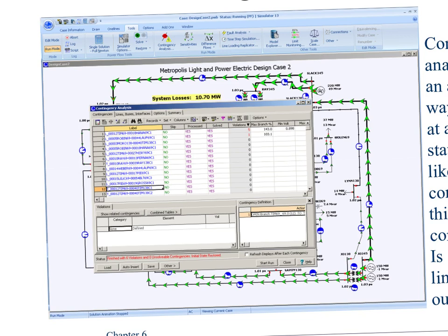So for those of you trying to maximize our efficiency and yours, here's contingency analysis, where you just enter a bunch of cases. Take this out of line, next. Take this out of line, next. Take this, and on and on, and you just walk through, and it's going to look for the worst case. This one actually automates the process of how to do contingency analysis, which is also what PSSE does. Most of us will not be doing that unless you go work, like I said, for ISO New England, or you do some analysis for generator projects.